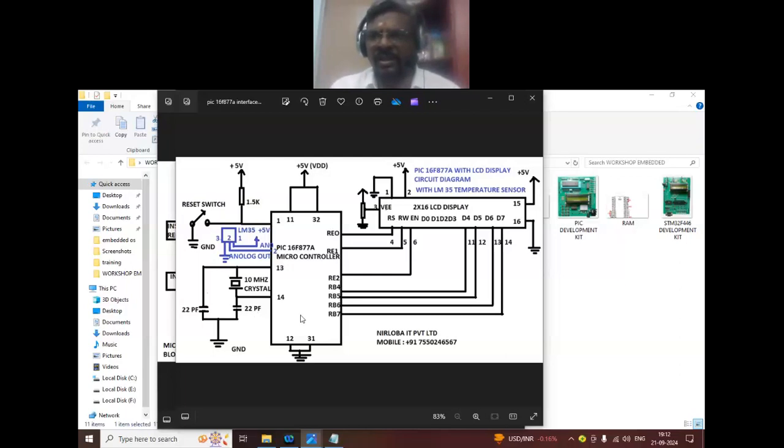This microcontroller is a digital circuit. For a digital circuit, the clock signal is very important. It should be the exact frequency, and it should have zero unwanted noise. Then only will the microcontroller do the task. Also very important, for any microcontroller you have to design a good power supply. It should be completely digital, since the microcontroller is digital electronics. So you have to give a regulated power supply. You can't use any other normal power supply. This microcontroller needs a regulated power supply.